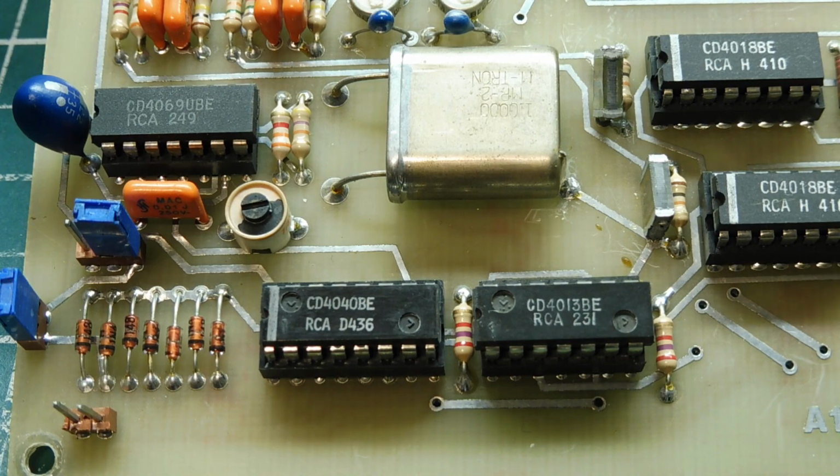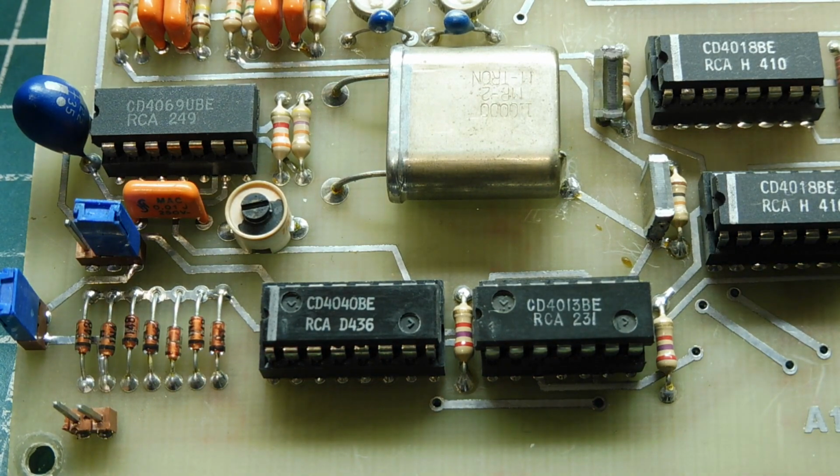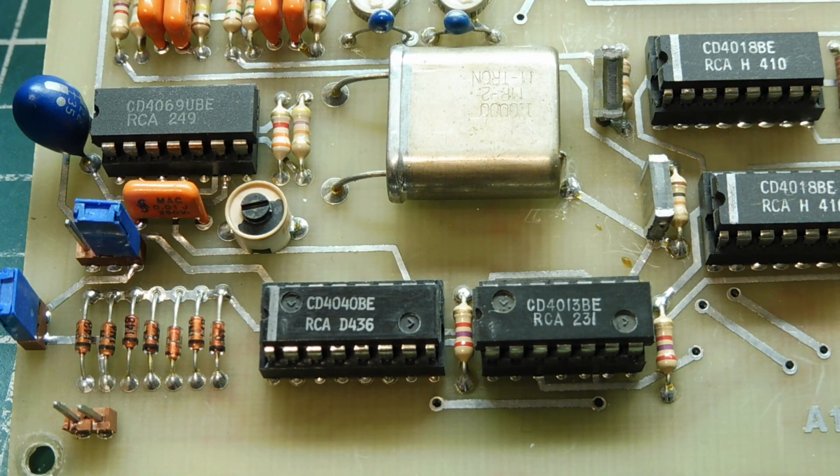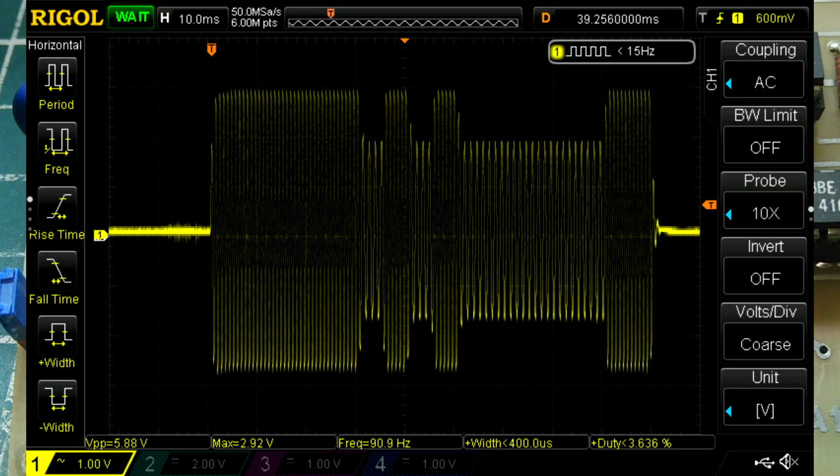Okay, next I am going to give some serial data to the FSK generator from a UART, and I'll give it 1 character, so it'll be 1 byte. So you'll hear the burst. So that's the burst. Now if we slow that down, this is what it sounds like in slow motion.